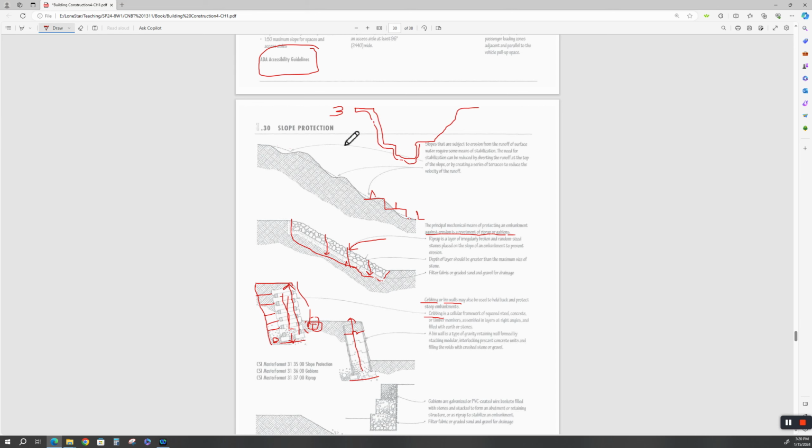But we're talking about something like this, okay? So we cut off and made terraces. But you got to be careful about your vertical velocity and how much water, because if you get a lot of watershed off of here, it's going to do something like that. It'll drop. When it hits, it'll start undermining the next cribbing or bin wall.